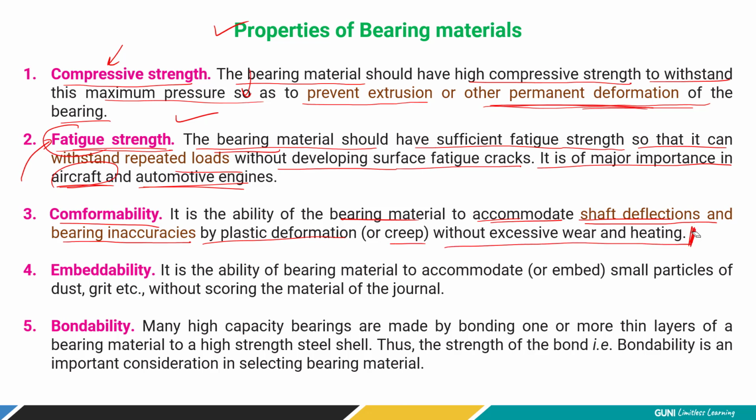So these are again the properties of the material required. It may deform, but it is not going to form any crack or create any excessive wear and heating. So slight deviation or deflection of the shaft is taken care of. That property of the material is referred to as conformability.